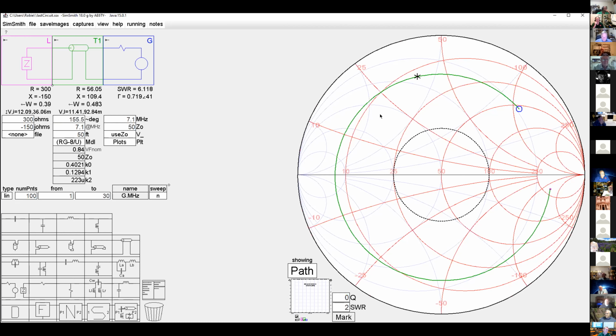So this is an example of the kinds of things that you can do with a program like this. And you can say, okay, 10 feet's pretty good. And 10 feet of coax is not very hard to come by, right? Just cut it, put a couple of connectors on it, put a barrel in between two of them, and man, you're back in business. So this is an example of matching with line length, which you can do.